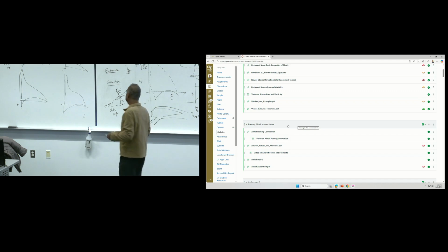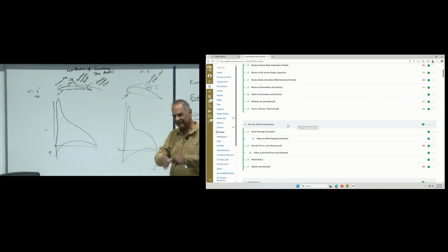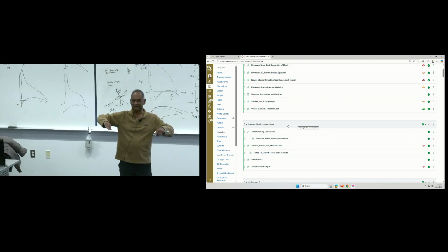Okay? So this laminar flow has all the high velocity up on the top, all the low velocity near the bottom. There's not a lot of mixing taking place. Therefore, when the adverse pressure gradient comes, it'll say, to hell with it, I'm going to separate. It becomes a leading edge stall. Okay? So early glider people, who had relatively sharp nose airfoils, were stalling very, very quickly. A lot of accidents were happening.